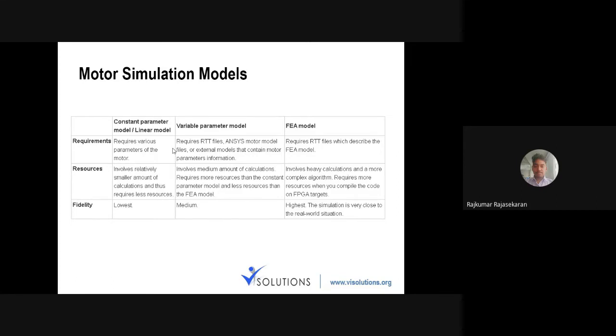And for real-time processing, it will require more resources on the FPGA also. An FPGA is not something like a processor. It is going to create a digital circuit to do your processing. It's not coding, it's creating a digital circuit. It's a fabrication of a reconfigurable circuit, and it's going to depend upon the amount of resources available in the FPGA.